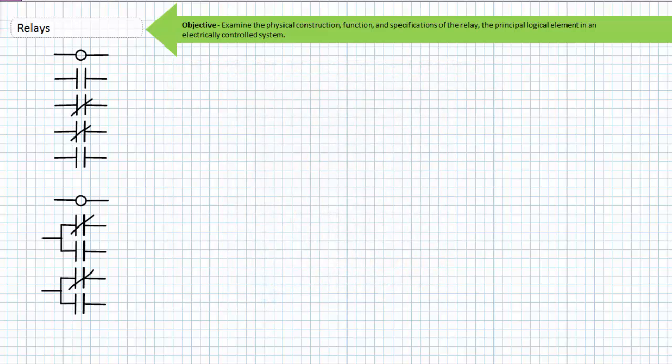Just like the contactor, a relay is typically characterized by a set of moving contacts that make or break a connection when commanded to do so by an electrically isolated, low-power control signal provided to the coil. Sometimes these contacts are electrically isolated single-pole, single-throw switches, as is typical for an industrial mini contactor relay. Sometimes these contacts are single-pole double-throw switches, with a shared common terminal, as is typical for an ice cube relay, sometimes called C-form contacts or transfer switches.